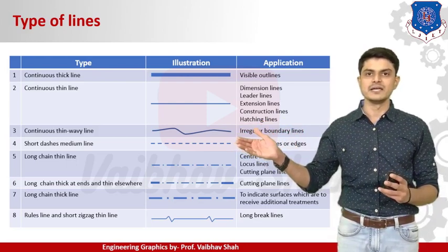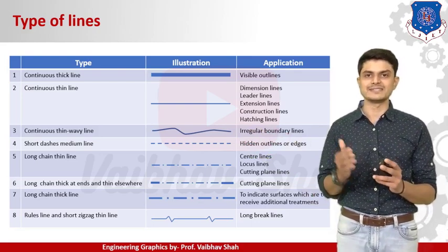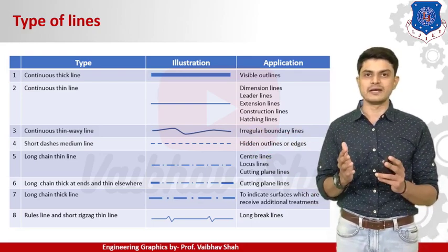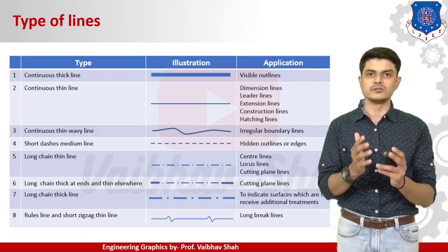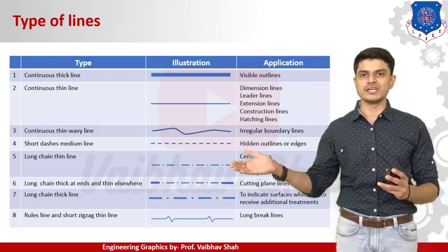We will be having equally spaced dashes like this. So it is usually used as hidden outlines. So whenever you are having any hidden object to be shown in your drawing sheet, you will be using these lines.